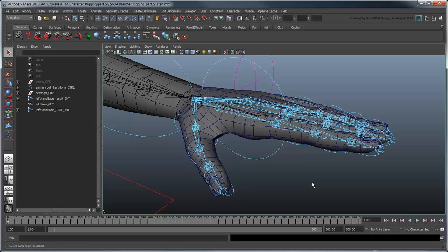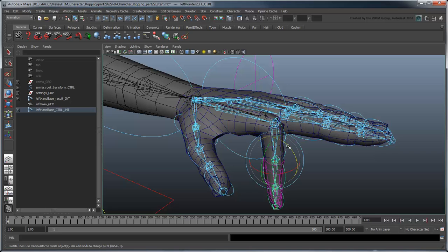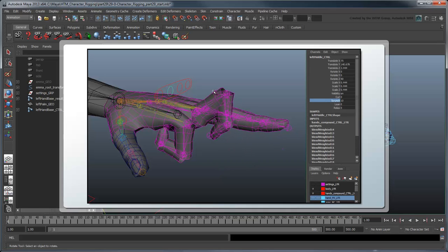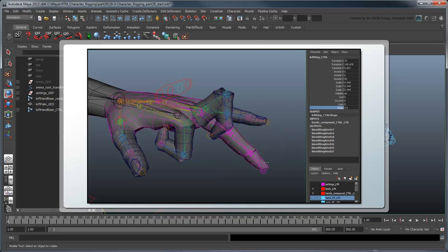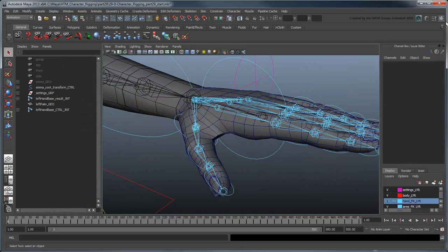While our current setup would actually allow us to animate the hand poses as is, it's not the easiest setup to work with. A simple motion like curling one finger would require keyframing 3 different joints. To simplify an animator's workflow, we're going to create a control curve for each finger and use custom attributes to drive some of these common compound motions. Hide the hand's FK layer.